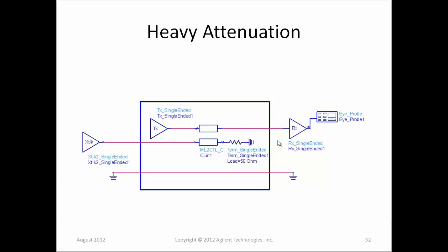So you really want a methodology, like those Wheatstone bridges, that measures the power waves without heavy algebra subtracting large numbers with noise on them. With a VNA, the voltage is directly proportional to the power wave. So even if you have a very weak reflected wave, you can measure it pretty well. So this is another reason why S parameters are measurement friendly. They work even in the case where you have heavy attenuation like a crosstalk situation.